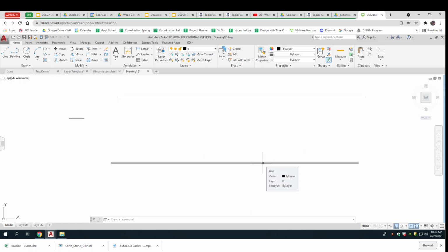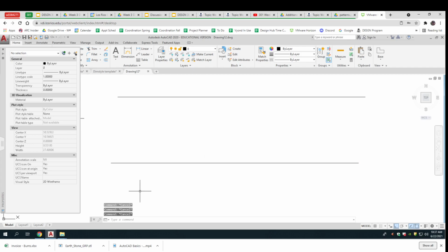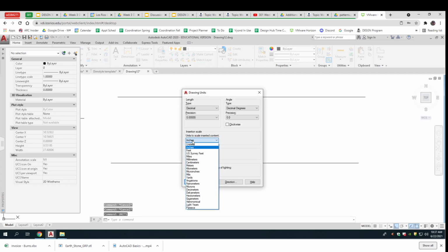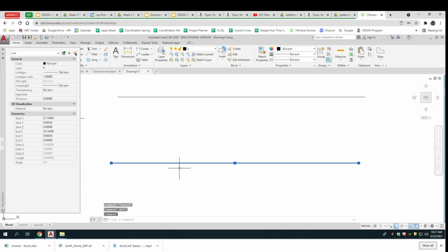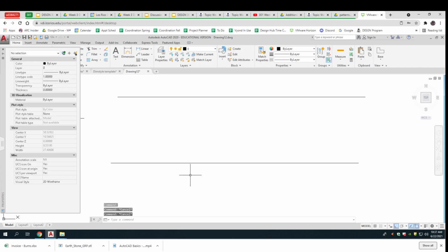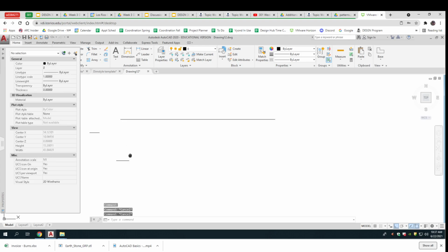Okay, but if I want this to be in decimal feet, remember, all AutoCAD knows is 16. So even if I set myself to feet, AutoCAD will think that that's 16 feet. And that was 16 inches long. So I would have to scale this, starting over here. What's 1/12? 0.0833333333. And now you can see that that's 1.33 feet. 16 inches.